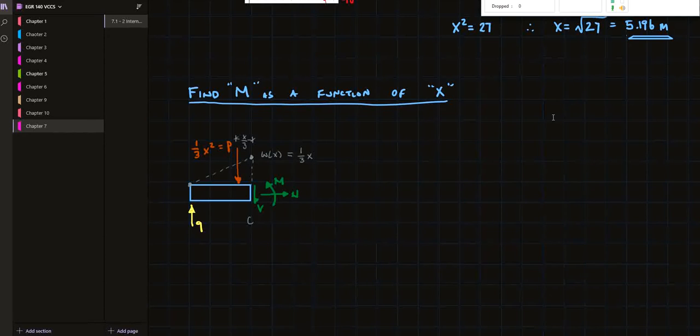All right, so let's now find an equation for our moment. And so we'll sum our moments about the cut equals 0. So the cut is right here where we cut this. And this equals, well, we have this 9 rotating in a negative sense. So, of course, we'll put this on here. Oops, let's put this the other way. Positive this direction. So minus 9 times the distance to the cut.